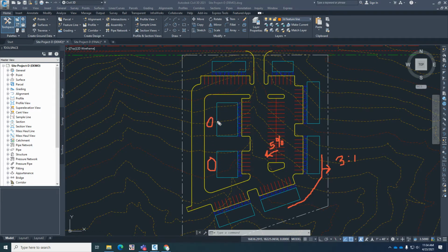Now, it doesn't have to be the 3-to-1. It just means that we can go up to a 3-to-1 if we need to. We can actually slope it quite a bit, and I think you will in some cases. You're going to have to be able to get this design to work properly, because if you consider the 3D geometry of it, these areas need to be sloping so that we get water to drain out to this corner on the flume, yet the building needs to be flat.